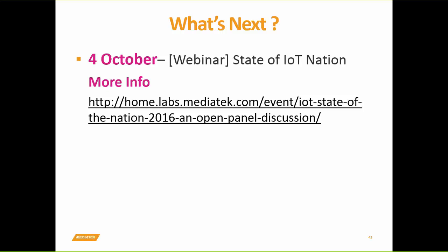Thanks, Phil. So that's all the questions we have now. We got another one regarding the use of Python: can we use Python apart from C? Unfortunately not, no. As I said, it's a real-time operating system. It's an ARM Cortex-M4 chip, so it's really an embedded system, which doesn't have the power to run Python scripts, so it's just C.